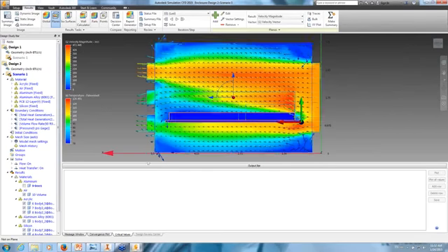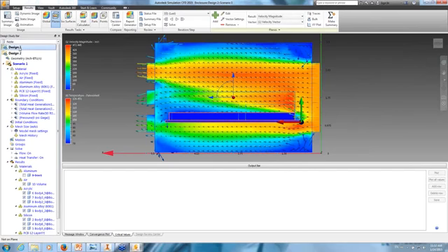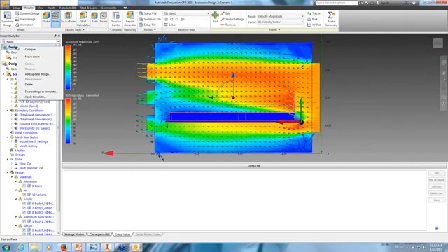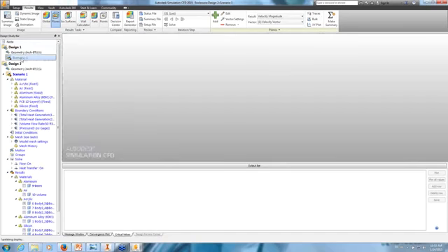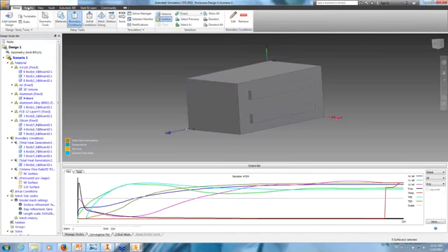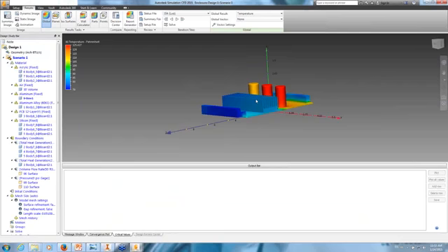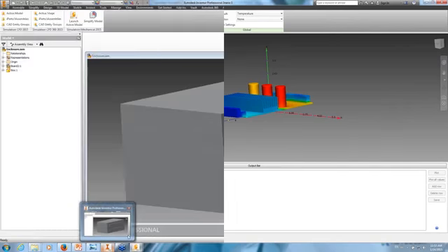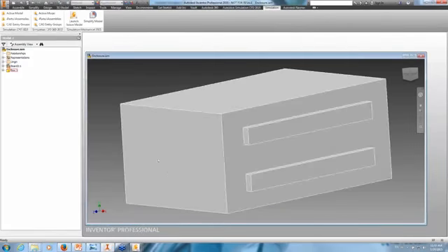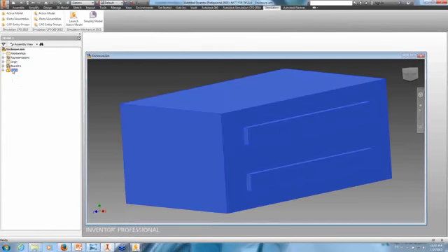So if we go back to design 1 and scenario 1 and activate that, you have to select the particular scenario under the design and look at the results. And if for some reason you decide that, okay, that wasn't good, I want to change the design. You know, in this case, we added 1 more outlet. So the way to do that would be to go back to your CAD model here, and that's going to be a real quick change here.